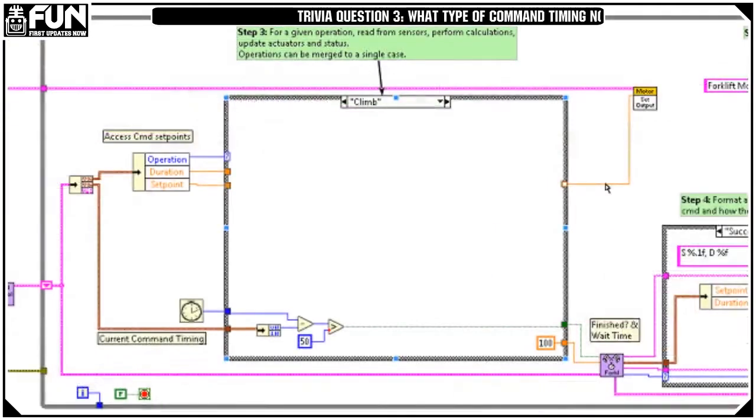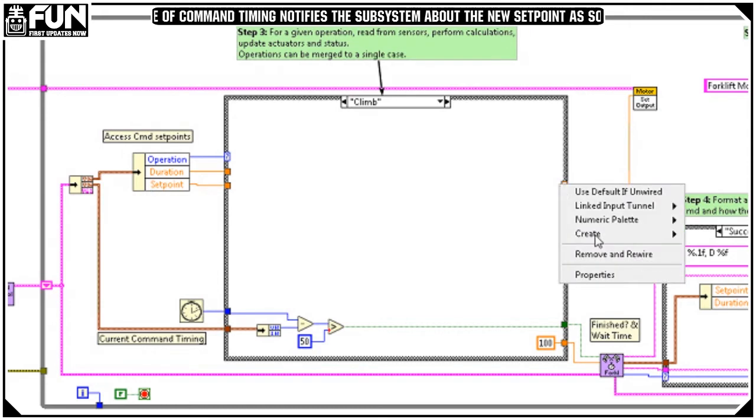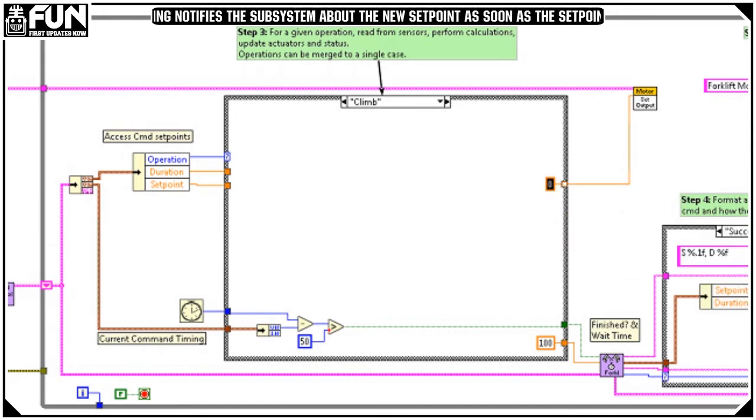And then for our motor output, say we did some testing and we found that when we go to climb, we just need the motors to operate at 90% of their total capacity the whole time we're climbing. So we're just going to go ahead and put in a 0.9, and the whole time this climb command is running, we're going to be operating at 90% motor capacity. This is a good idea to not operate at 100% motor capacity because that's how you can get brownouts and things like that, which are not good when you're trying to climb a 7-foot tower.